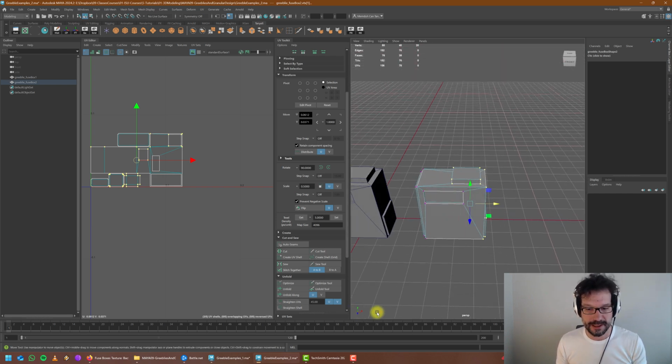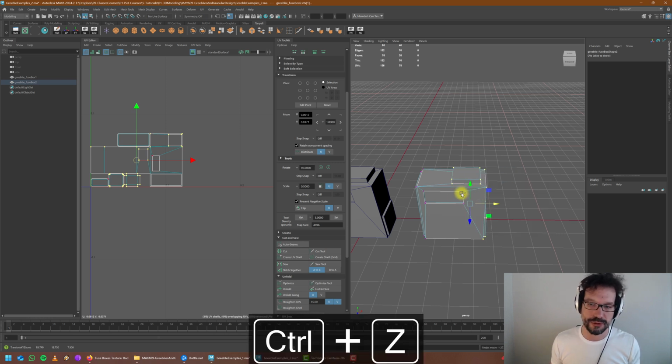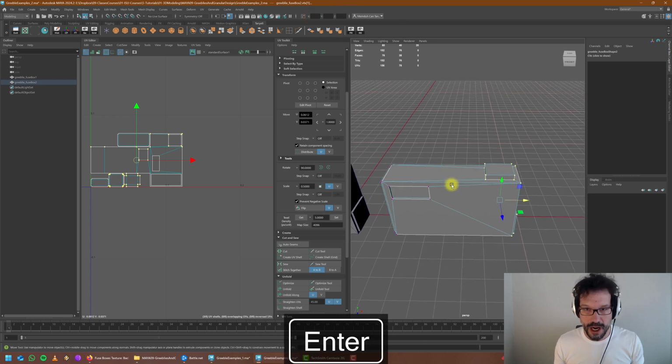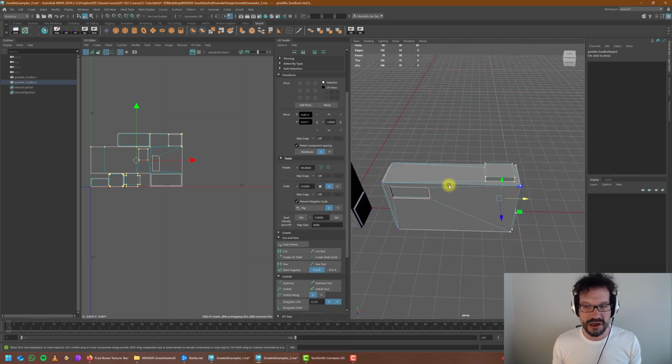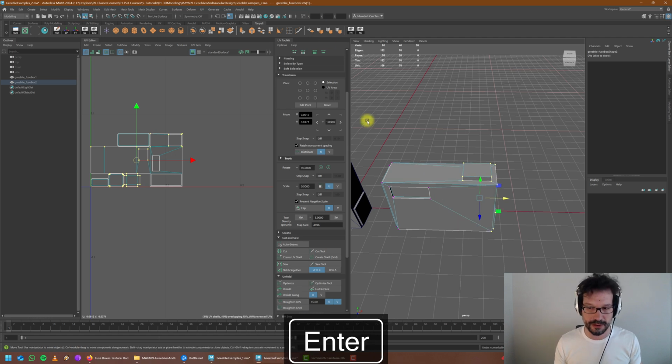So look at the orientation right now of the coordinate system. You can see that this is X, which means if we are seeing the color and the reading, that's the positive X side. So we want to push these on the positive X side to elongate this object, so to speak, and I want to elongate it by, I don't know, 30 centimeters. I can just type in 30 here and it will do so. Maybe this is a bit too much. Let's get that back. Maybe let's go with something like 20.